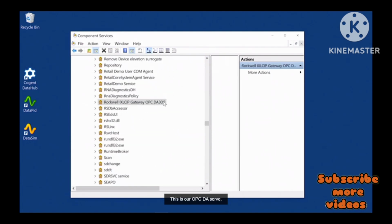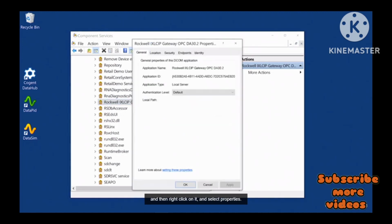This is our OPC DA server. Right-click on it and select Properties. This is where you can find more information about the OPC server: the application name, the application ID, the type, etc. I'm using the OPC client Cogent Data Hub on the same computer, and I didn't need to use all this information. But sometimes, if you are setting up the configuration on the client side over a network, you might need to have access to this information shown here.